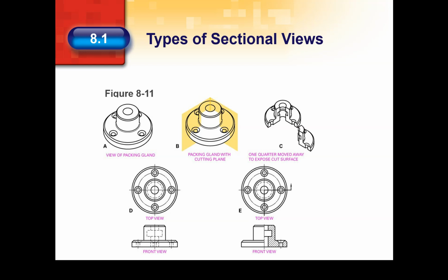If the direction of viewing is needed, use only one arrow. See figure 8.11e. In the top view of figure 8.11e, the cutting plane line could have been left out because there is no doubt where the section is taken.